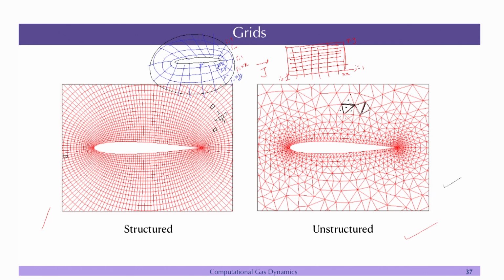All you have is, let us say if you define a direction or normal to the flux, you can have a left cell here and right cell here. Let us say look at here. So, this is my edge. There may be left cell here and right cell here. That is the only information that we have in this kind of grids. So, you can define left and right cell on every single edge or interface, but you do not have the information of connectivity. The second problem that you have is how do you basically define the upwinding here.